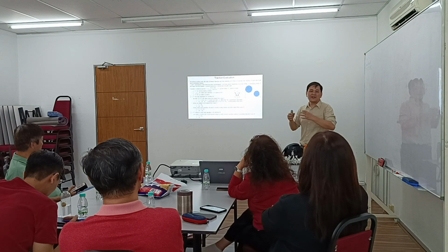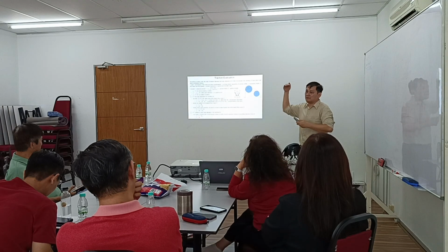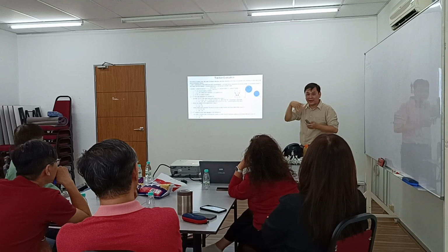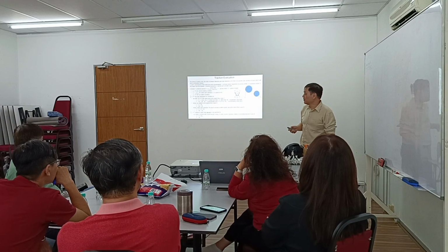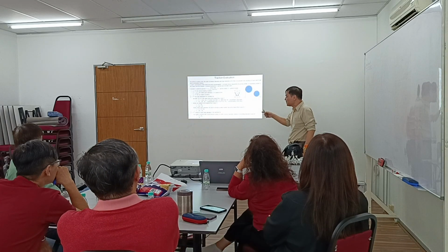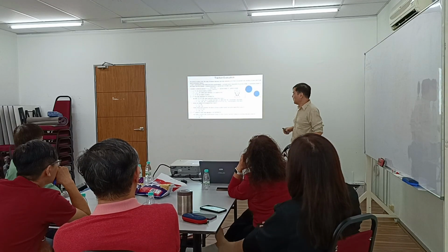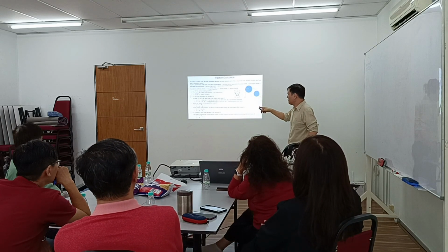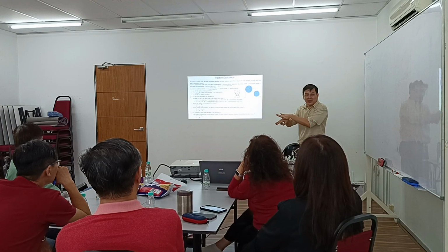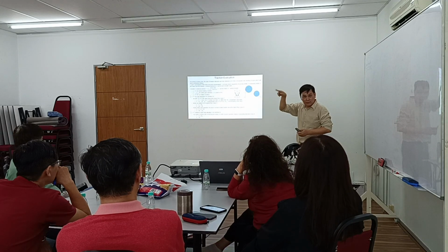What will happen if, let's say, the safety gear is engaged, the car stops and the rope slips? That means the rope will still run, so it will cause the loop stacking. So this is also dangerous. But in one circumstance we want rope slippage, whereby the lift car stops and the counterweight already hit the buffer, resting on the buffer, and the traction lift machine is still moving.